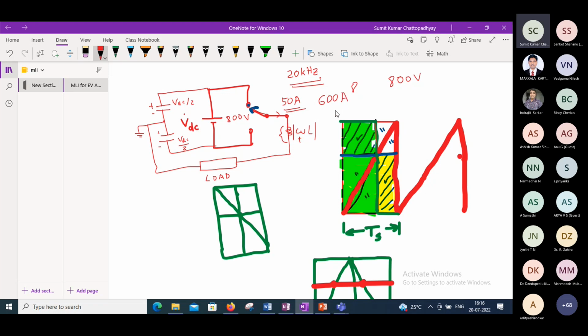Of 600 ampere. Pardon? So 600 ampere. And why this 600 ampere? Because it requires significant derating to accommodate the heat. Now, why 20 kilohertz? Of course, what power quality is available with 20 kilohertz, we can easily get with a multi-level converter where the final volt-ampere rating will not be this high.